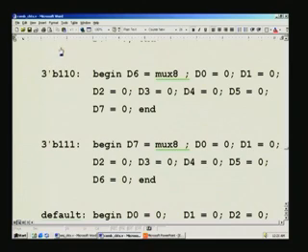Another point I may mention is, you have put everything in a sequential order, say a binary sequence, but there is no need for you to do so. And also this may be painful to write with so many bits. If you have 64 inputs, you will have to write very many, and the larger the number, the more you have to write. So, a better thing would be to use decimal here. You can just replace this B with D, but even in that case this will mean only the number of bits. So, you have to take the trouble of first computing how many bits it will run into at maximum, then put this. So, this tick is a prerequisite here, and this colon is also a prerequisite here,